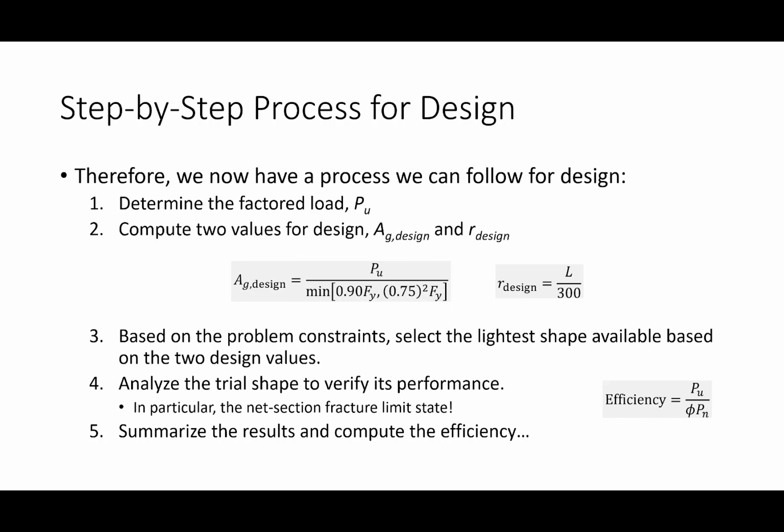Our step-by-step process for design, and again, that's another one I missed, I'm sorry. I redid my slides this time and I had a boo-boo. Okay, so whenever we design a tension member, the first thing that we're going to do is determine the factored load that may be given to you, or you may be given service loads that you then need to factor, okay?